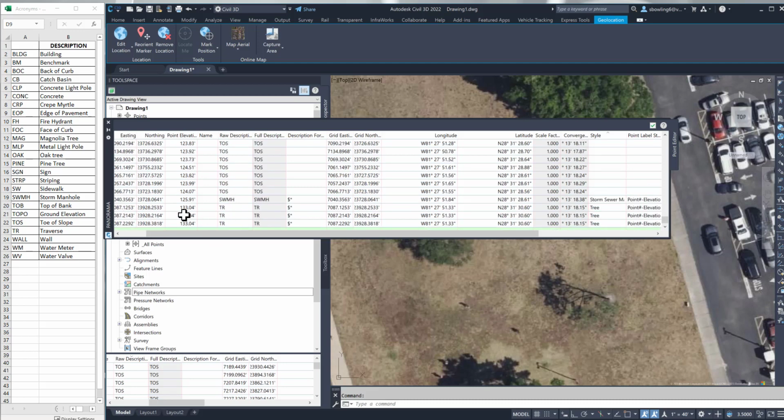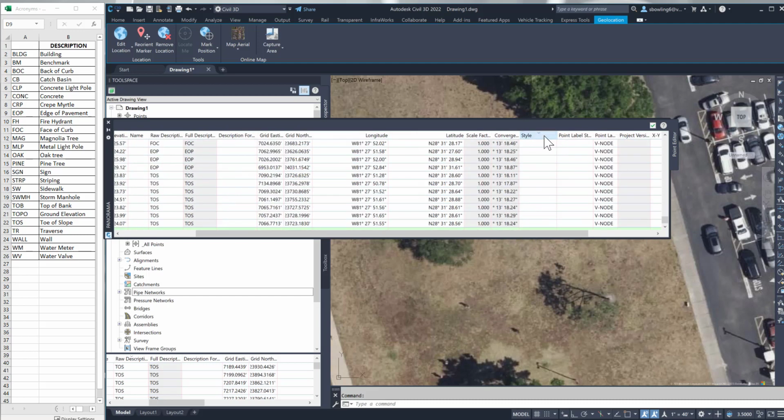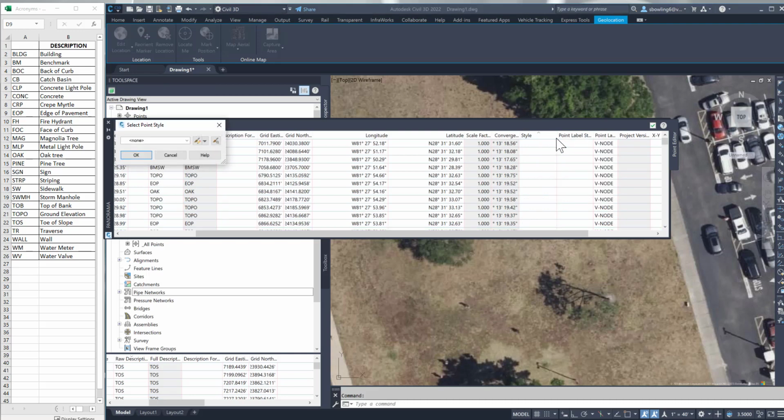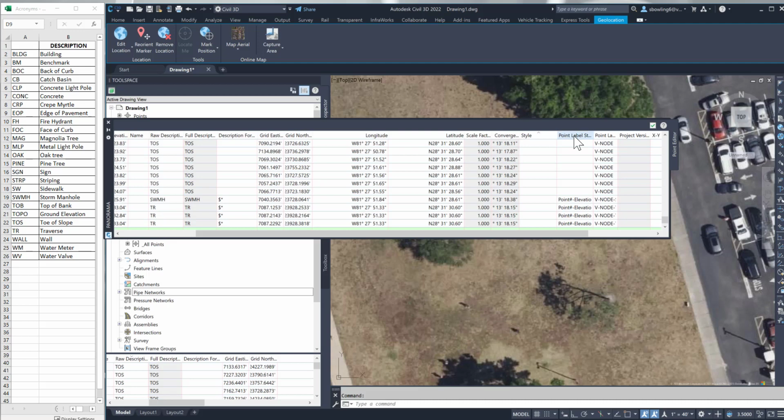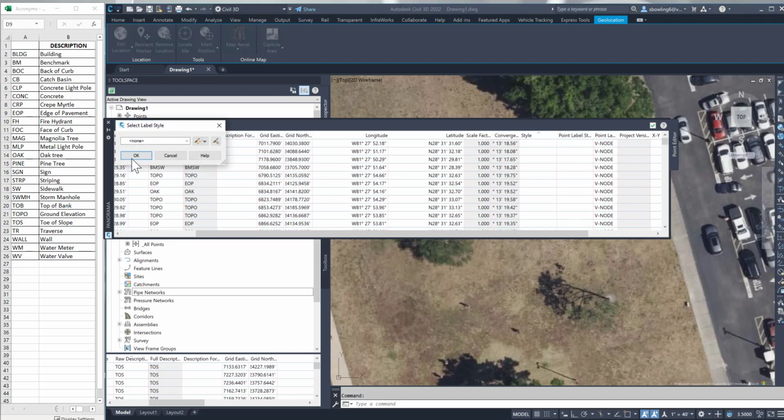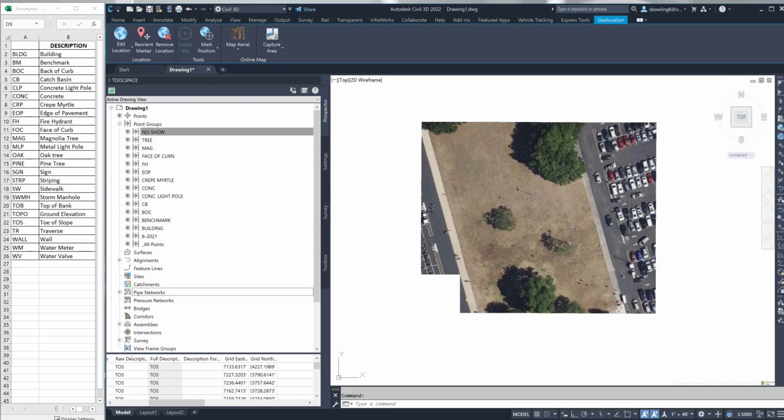These will show up because they have a style associated with them in that group. So if I wanted to not have that style, I can click on this. Okay, so I'm highlighting it, but I'm not touching anything. I'm just hovering over the style. I'm right clicking and I edit. When I edit, I click on none, and the same with the point style. Right click, edit, and none. Okay. Now all of my styles are gone.